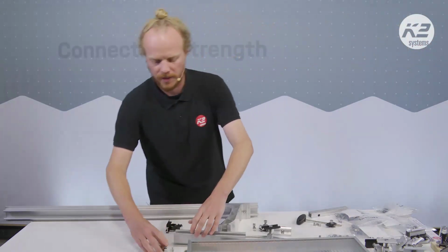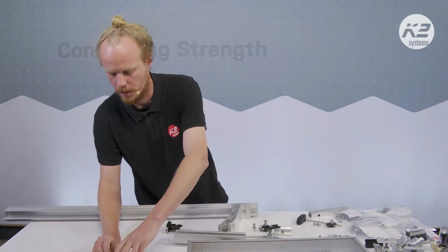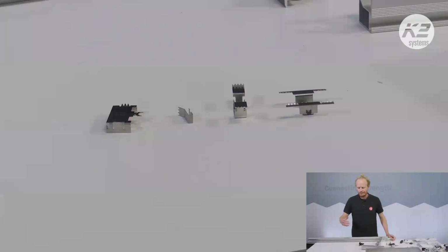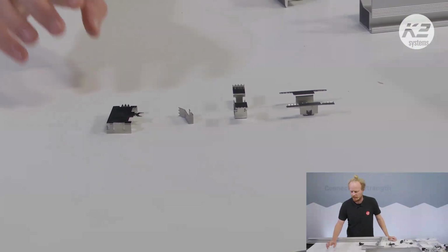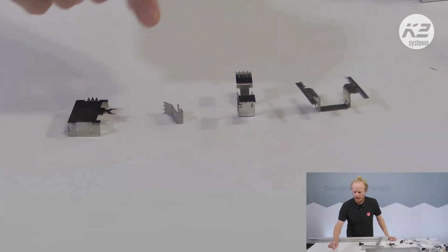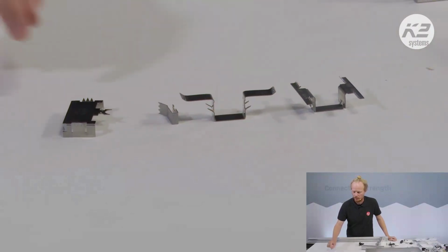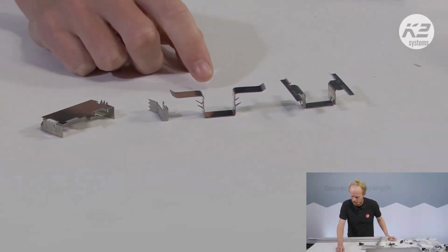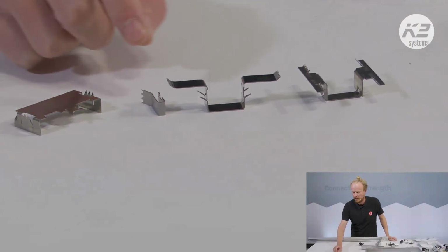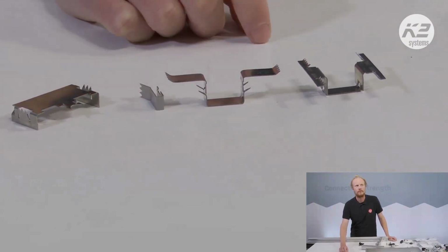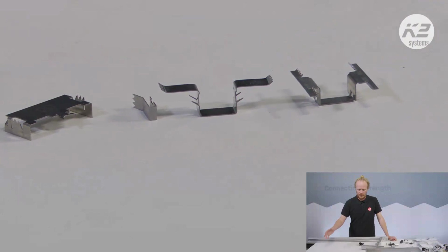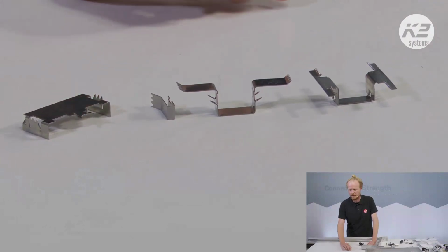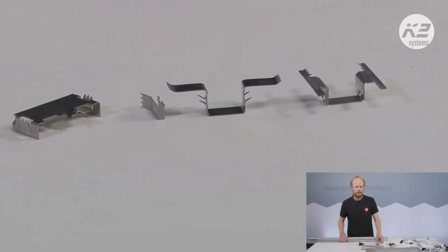So some of the products that we have, and you saw them before, are just lying now in front of me. Generally speaking, they act in the same way, or they have the same purpose: all of the products have some little teeth on them. So you also have to be a little bit careful if you're rummaging around within a bag, because they are quite sharp. The idea behind all of these little teeth is to scratch the surface of either the rail, which I have behind me, or a module frame, and ensure that there's an electrical contact between the two.